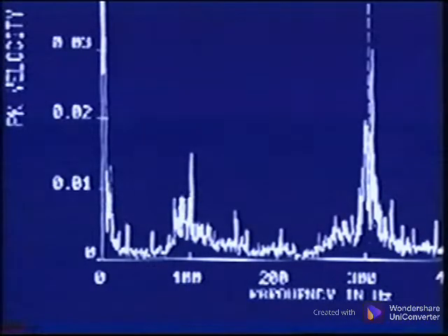The natural or resonant frequencies can be determined using an impact test. Of course, the testing should be done while there is a load against the teeth, so it will resemble the gear load as it is meshing. The key here is that this resonant frequency will be modulated by side bands spaced at shaft speed.